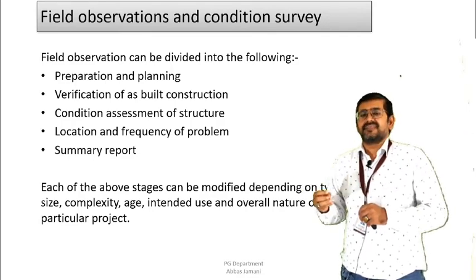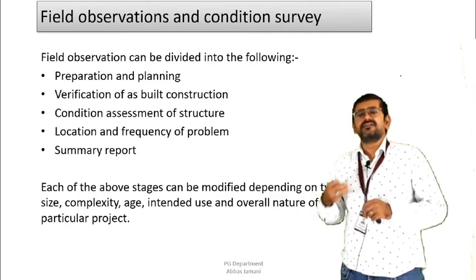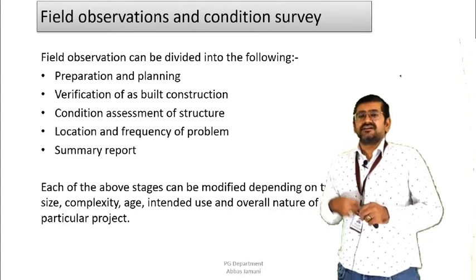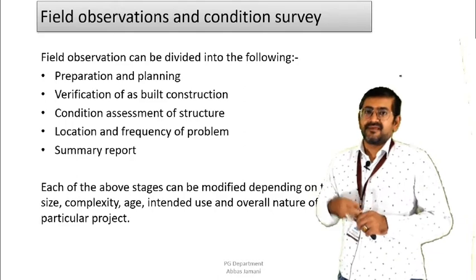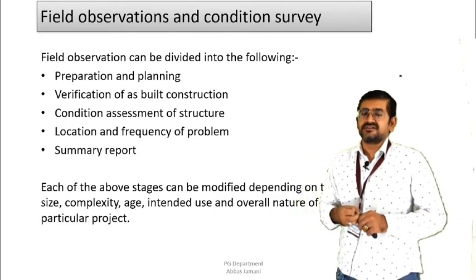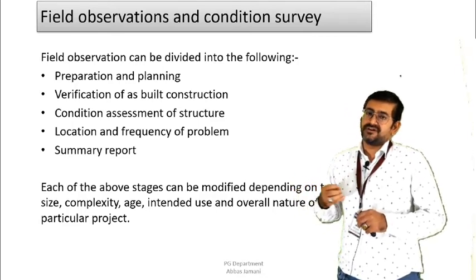Everything will be noted. If cracks are there, what is the width of the crack? What is the depth of the crack? What is the location of the crack? You take some photographs. You make a video wherever necessary. Right? If any uneven loading is observed on the site, you take note of that. What is the cause of this loading? What are the causes of changes or maintenance that was done over a period of years? These are all different things that you observe on site and you record them into different categories.